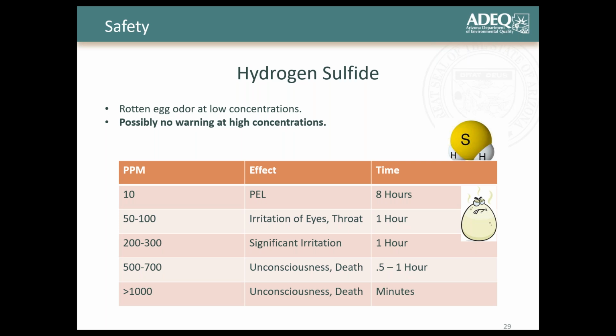It was common practice for us, and I recommend you analyze the best practice for the area you're in, that if we saw any bit of hydrogen sulfide in our confined space area, we would evacuate, ventilate, and take every precautionary action we could. And even when you smell that rotten egg odor, it doesn't take very long before you go nose blind to it. So be aware of that. You may smell that initial rotten egg odor, and then you go nose blind to it pretty quickly.